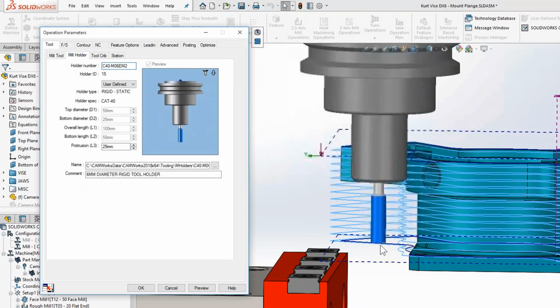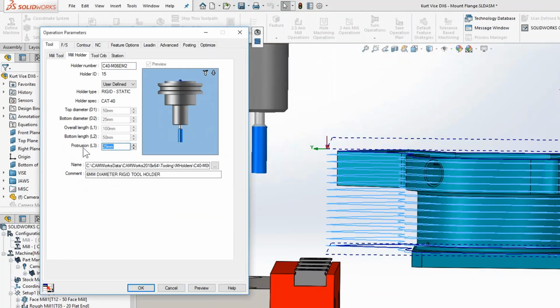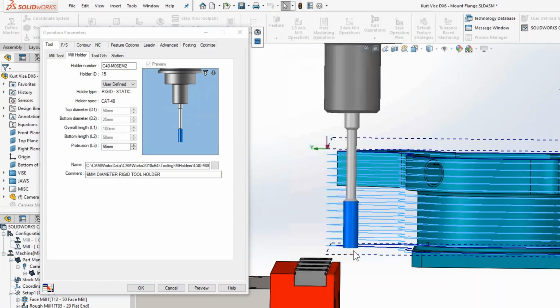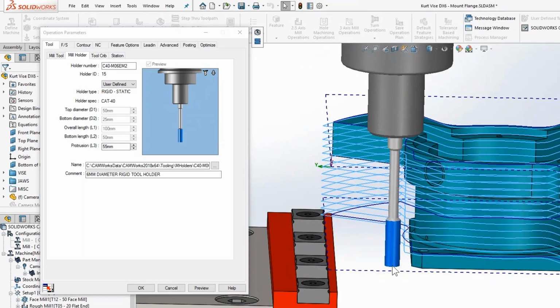We also have control over tool holder. Now, not necessarily new with 2019, but the shape of the tool and the size of the tool holder get incorporated into the simulations to warn us if there's any gouges on the part. Those would actually be visible, and you can run these simulations of the tool paths and the part being cut digitally before you get out and wreck any metal.